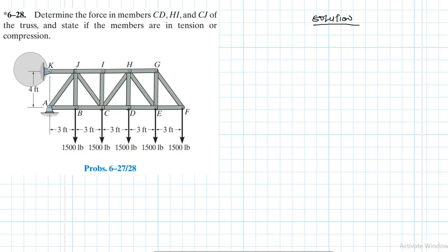So this is also very vital to notice. You need to notice that quickly when you are drawing or working out, so that you don't get confused. Because of course you would say, since this is a hinge, you are going to have two reactions like this, but this component will not be there, right? So I'll leave it out. So I have KX like so, and then here I'm going to have two reactions because of this horizontal member.